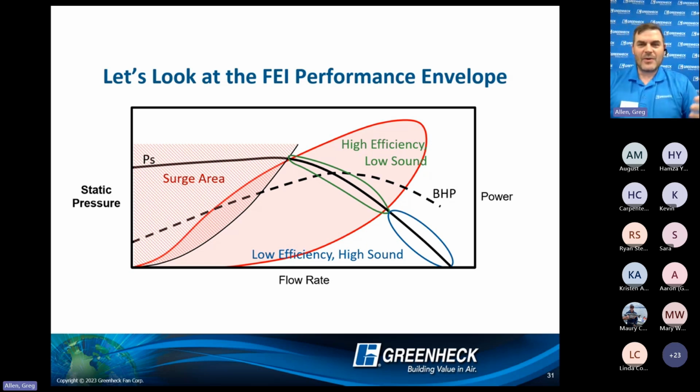Now, kind of back to all that information, if we were to change the RPM up and down, you can see where I'm getting a narrower spot of peak operation or a little bit wider spot. These are all values where this fan is a good choice. If you're outside of that, you're going to have an FEI lower than 1.0. And this is really rolling into a lot of the regulation requirements, where an average good fan would have an FEI value of 1.0.